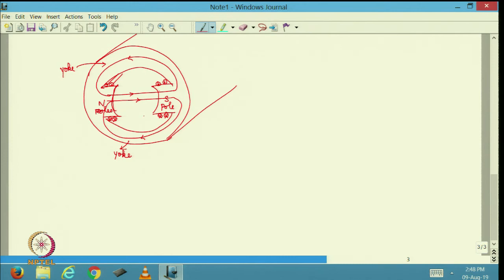Now, because I have the magnetic field here, if I put one conductor here and one conductor here, you can imagine as though the conductor is going inside, then it has to turn around and come back through this portion, and ultimately here I am going to connect the load. This portion is outside the purview of the magnetic field. You can imagine that the pole is going here. So, this shaded portion is essentially the pole.